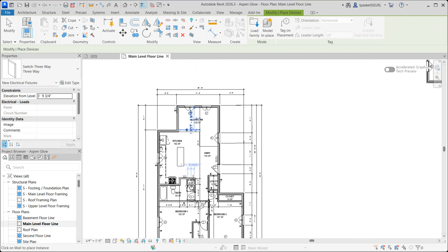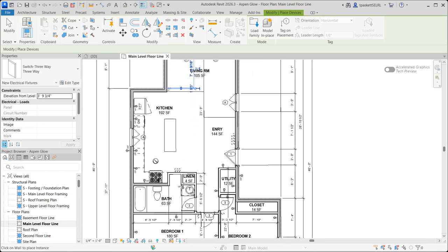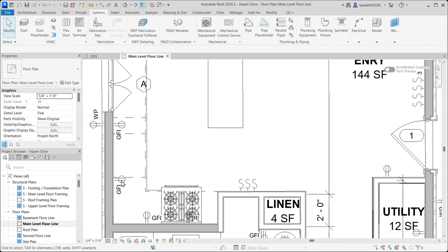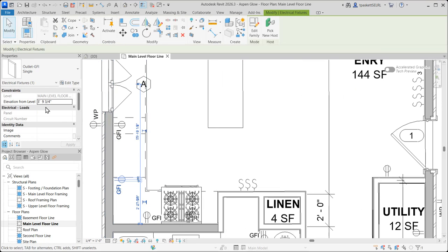Okay, and so this is what you then do today. You're going to finish up what you didn't finish last week, and now you're going to add the electrical. Don't slow down on these. We've got a lot to do, so keep going. Don't stop, but get your outlets in there. Make sure your outlets in your kitchen, when you select them, you have to do a window to get them. They need to be 42 inches off the floor.